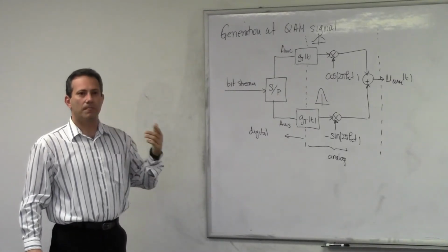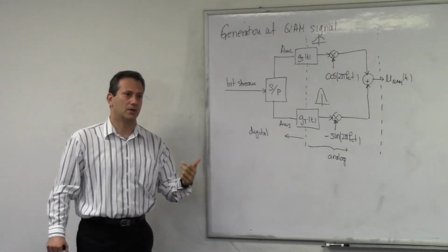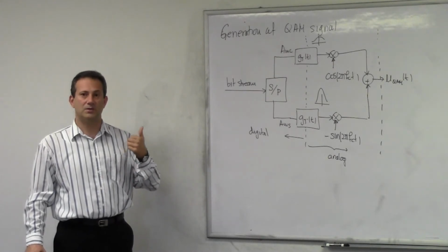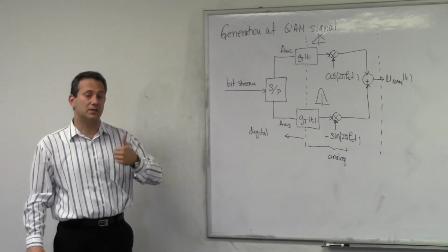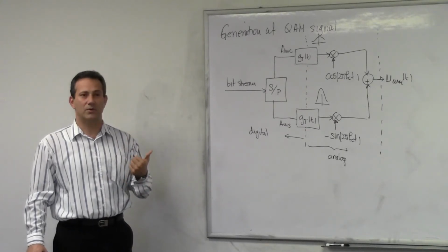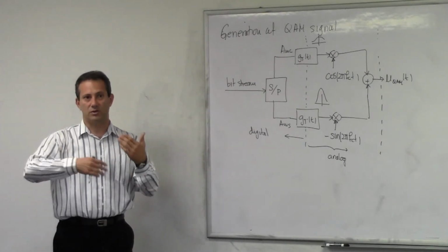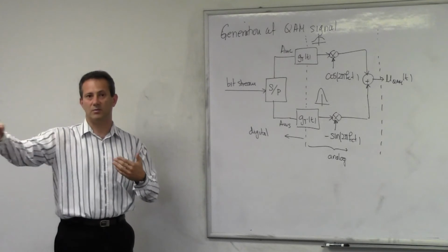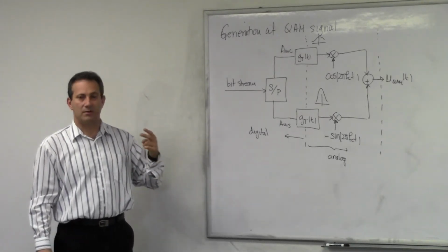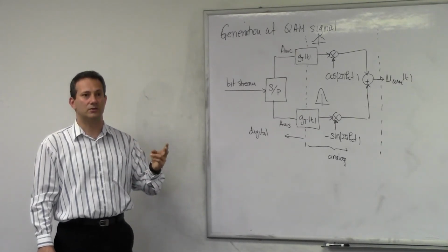So these are the two. We kind of covered three modulation schemes so far. We covered one-dimensional pulse amplitude modulation. And that one we said you can signal at baseband and you can signal at bandpass. But most of the time we use that one when we signal at the baseband, right? You don't have modulation up or down. You're just forming bits and sending them to the other side. The second type of modulation we covered was two-dimensional modulation, when you signal along two basis vectors.